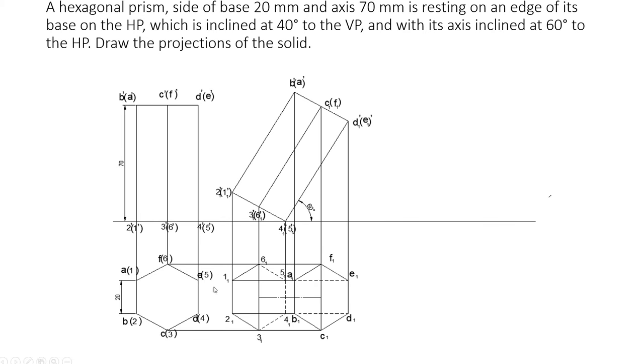So all the lines to the points 4 and 5 will be invisible in the fourth diagram. For that, you have to consider this method. Of the top and bottom points, whatever is coming on the right side of that, that is 5 and 4. Since the object is turned towards right, the points on the right side, 4 and 5, all the lines to the points 4 and 5 will be invisible in this case.